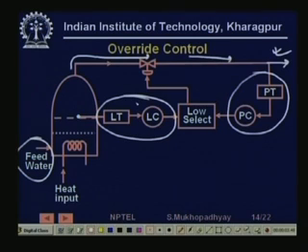So we will not draw steam from here, and similarly if the pressure goes too high, then also we should close the valve, so the pressure will be controlled. Depending on these two modes, closing the valve means a lower input, opening the valve means higher input. Whichever one needs to close the valve, that one will be used. So in one situation one control strategy will override the other. That is why it is called an override control.